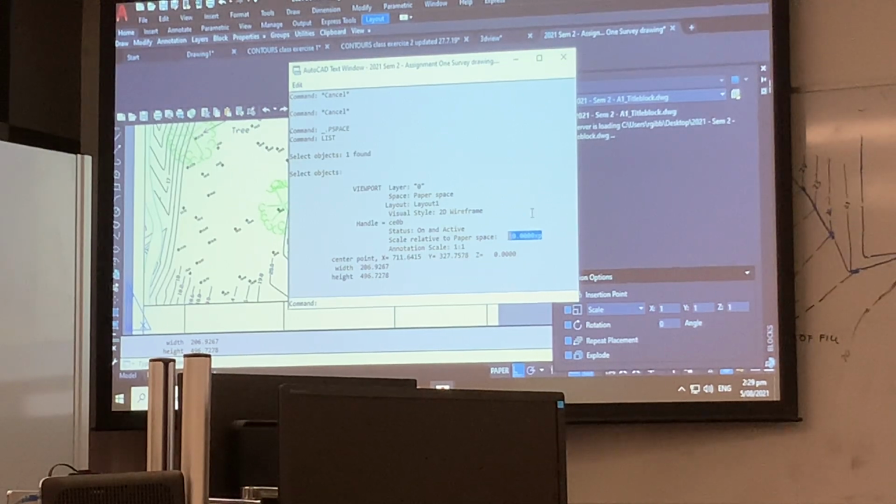You know, the length was different. The guys on site were ringing up saying you've got the wrong length. You know what? He'd done his viewport wrong. He'd brought the scale up too much or too little. We went round and round in circles and found that was the problem. The title blocks matched up perfectly. Everything matched up, the logos. It was the scale of the drawing that was wrong.